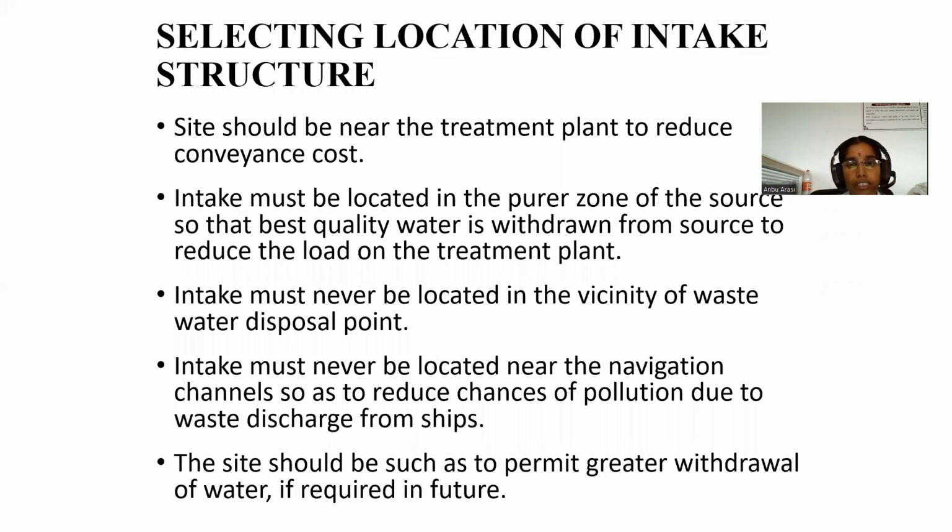Site should be near the treatment plant to reduce conveyance cost. Intake must be located in the purer zone of the source so that the best quality water is withdrawn from the source to reduce the load of the treatment plant.